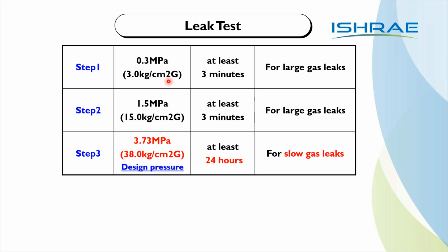Then step 2, you need to use say 15 kgs. 15 kgs is about 225 psi. Again, at least for 3 minutes for large leaks. Then step 3, 38 kgs, that is about 500 psi, or the design pressure. Please note this, it can be even 35, it can be 30. Again, you have to refer to the manufacturer's manual.